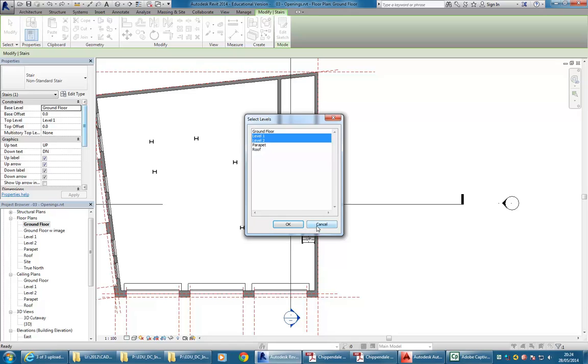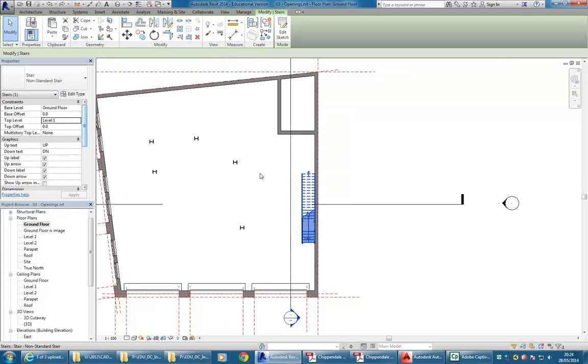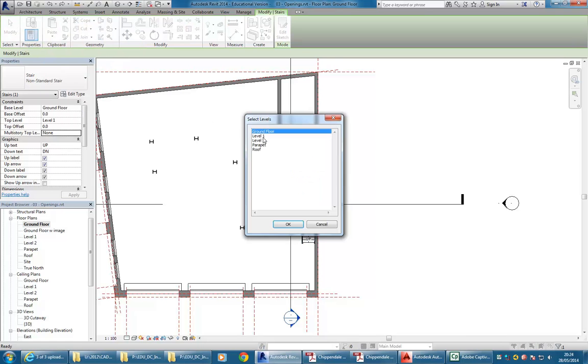So you might have noticed or seen with other things, when you select any stair, you've got the option of setting multi-story to go to a higher level. And that's often a good way of doing stairs through multiple stories. But when they're different heights, that option doesn't work. So it's only when you've got multiple stories that are the same height. Otherwise, you need to use this method I'm using, copy it, and then paste them aligned to the levels you want.